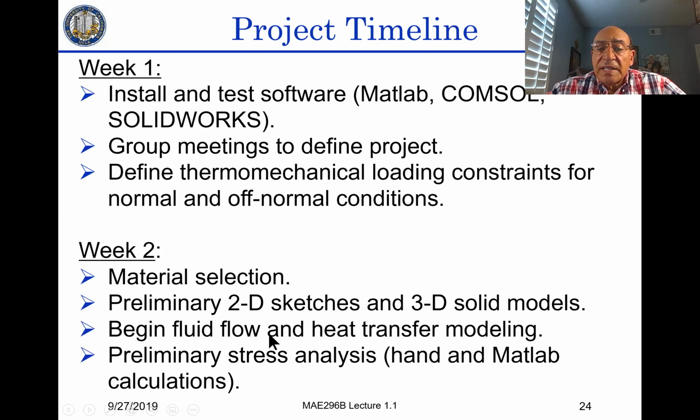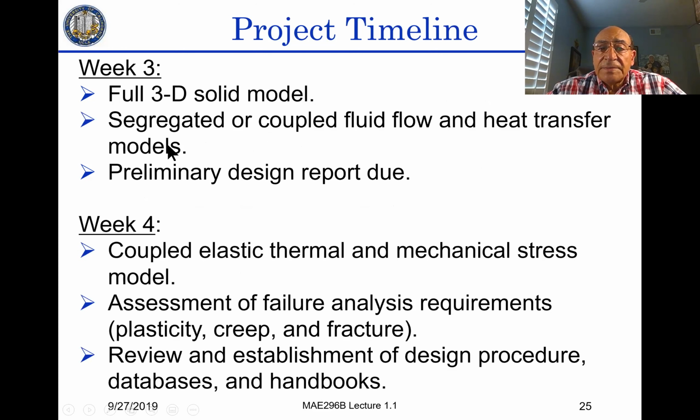And then you begin fluid flow and heat transfer modeling and some preliminary stress analysis code calculations. Week 3 is you do the full 3D solid model. So it's pretty fast once you get to that stage, and you prepare a preliminary design report, and then you can submit it at the end of week 4.